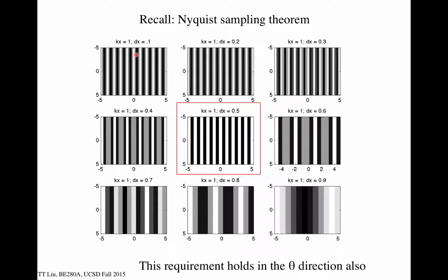If I sample with a higher frequency, I do represent that function well enough, right? This is the cutoff at which, when I have, say, a spatial frequency of 1 cycle per millimeter and my delta spacing here is a half, then I start getting this full cycle, right? So 1 up, 1 down, 1 up, 1 down. And that's the Nyquist sampling criterion.